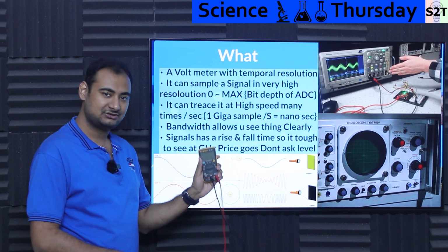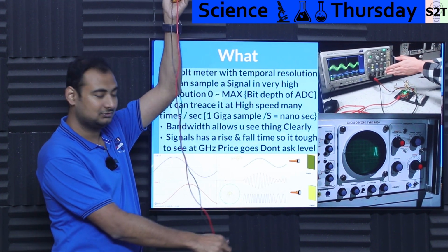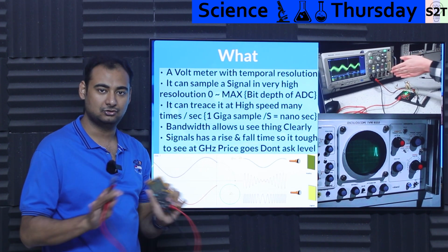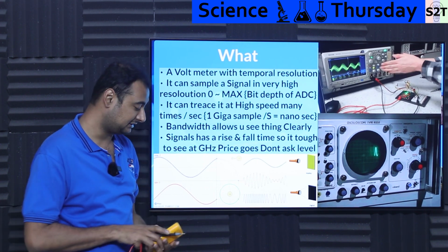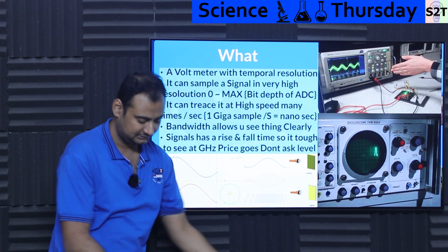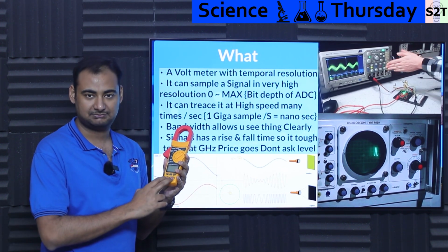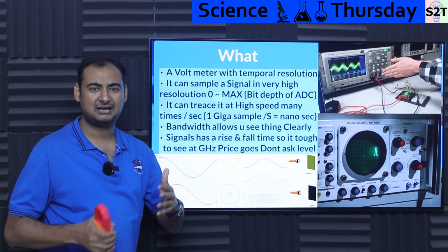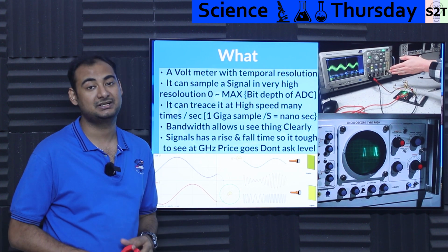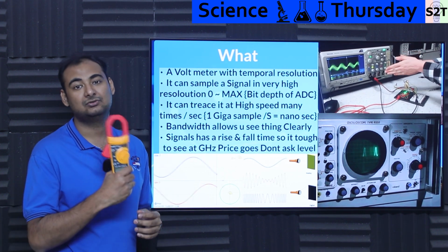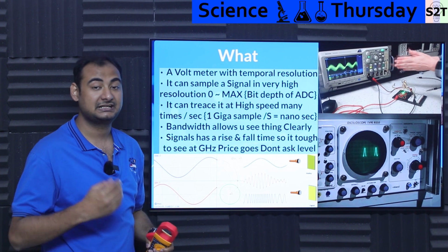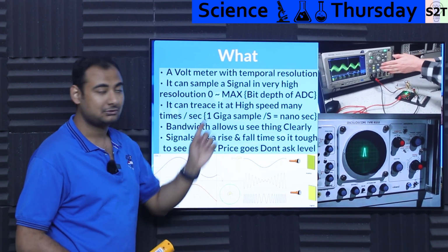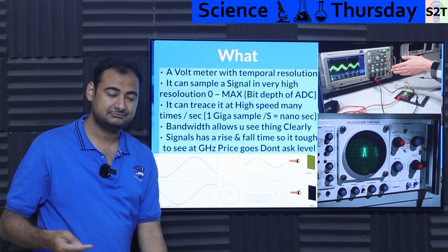Whenever you are talking about this sort of meter, all it will do is give you one reading. Basically, you point it, it gives you a number, the end, go home, sweet dreams. Or at best, if it's an AC meter, designed for AC, you use the probes and it tells you it has this much, basically averaging RMS, that's it, done. It only gives you one rating. So basically it has no temporal resolution. It can give you the amplitude but cannot give you temporal data, meaning what's happening to the signal throughout time. That is unknown.